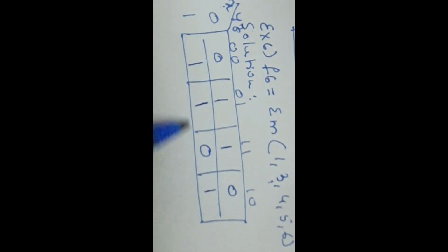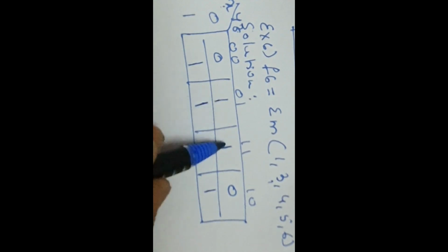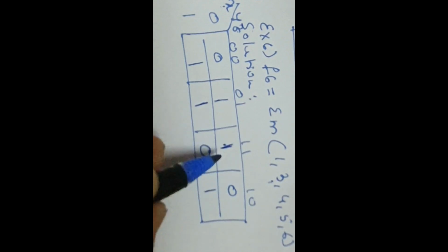Next we have to group. So can we make an octet here? All 8 are not ones. Can we make a group of quad? These we cannot make, 0 is here. This also we cannot make, 0 is here. This also, 2 zeros are there. Then a rectangle anywhere we cannot make. So a quad is also not possible. Next what shall we do? We shall try for pairing, right? So these two are adjacent ones. To cover this one, this only we have to draw.